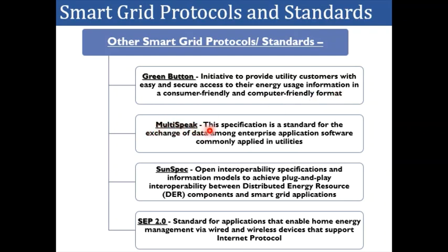Then MultiSpeak, this specification is a standard for the exchange of data among enterprise application softwares which are commonly applied in utilities. SunSpec is an open interoperability specification and information model to achieve plug and play interoperability between distributed energy resources and smart grid applications.